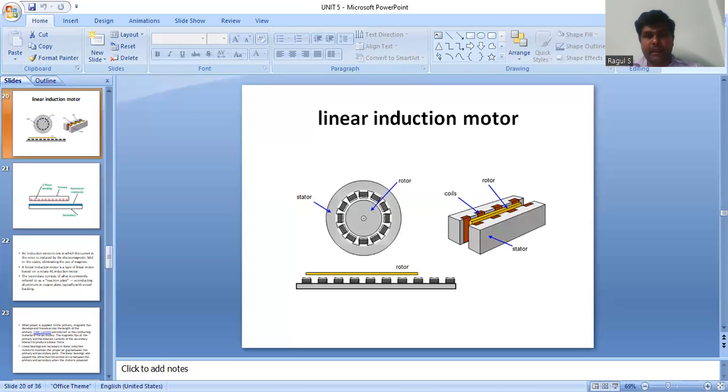Depending upon the particular requirement, either member can be the stator, the other being the mover of the motor. In the primary we prefer a ferromagnetic plate. It is placed on the other side of the conducting plate to provide a path of low reluctance to maintain the main flux.